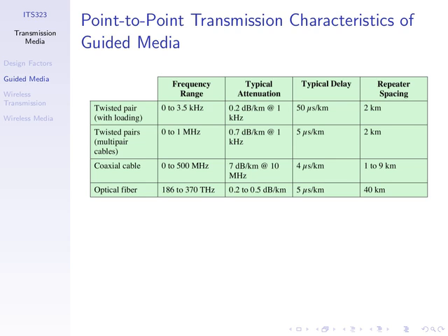Remember, our signal gets weaker. It attenuates across distance. By how much? How much power do we lose across distance? We know that we can measure loss of power in terms of decibels. So here are some numbers. For example, 0.7 decibels per kilometre if we're transmitting at 1 kilohertz. So different characteristics in terms of how much power is lost. Signals have particular delay and typical spacing between repeaters, or maximum cable lengths given there.